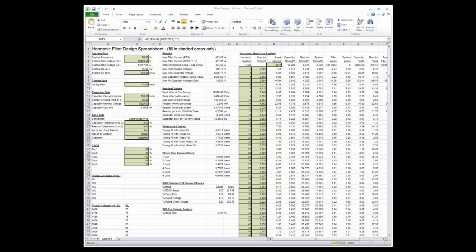And that is the reason why we typically apply fairly large size single tune banks, because when you're doing a lot of switching of banks, you've got all the additional reactor costs, and all the vacuum bottle costs for switching. And the other reason is, believe it or not, if you apply a 5th harmonic filter, it will absorb 7th. It will absorb 11th. So it's not just filtering only 5th out of the system.